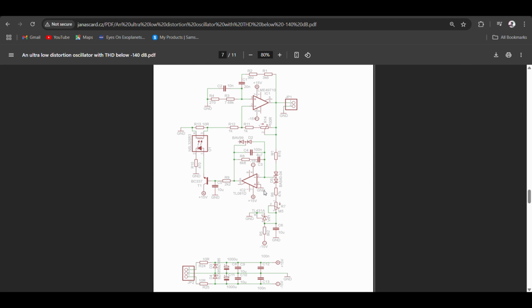So it features one LCR in here, which is our gain control unit, and this full part with the IC TL081D is a part of the AGC. I mean, together with the LCR and this op-amp, this is a part of the AGC, or automatic gain control. I'll definitely explain the circuit in a minute.